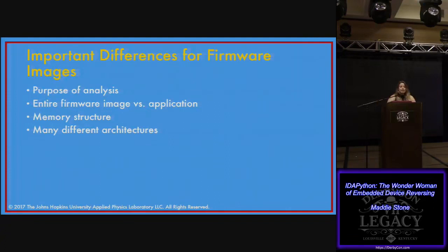Another important piece that's different is our memory structures. A lot of microcontrollers are using Harvard architectures, which means that the instruction and code bus is separate from your data bus. And so how are you going to understand that this code over here is actually reading and writing in the memory over here? Because IDA doesn't always process that clearly.